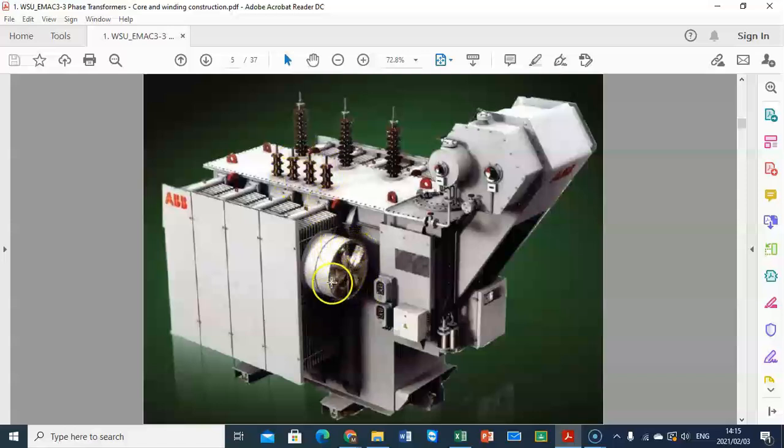And what you see here is a fan. So in this case, you have a forced secondary coolant method, because if we have just the radiators and we don't have any fans or pumps, it means we don't have any force. But here we are cooling the radiator also with a fan.